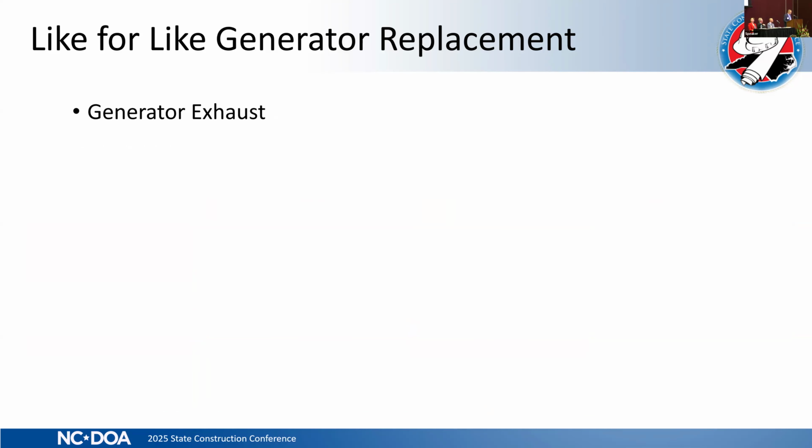Okay. When the new generator was installed, we did a NFPA 110 generator test, including a full load bank test. And I mentioned earlier that the loading dock and the generator room were below grade, basically the basement of the building.